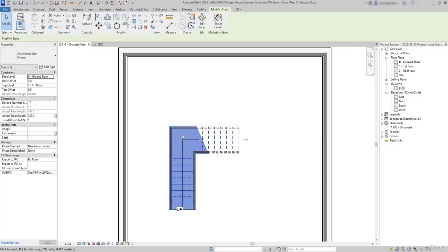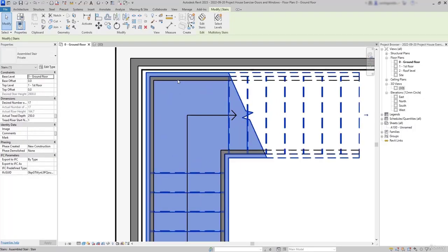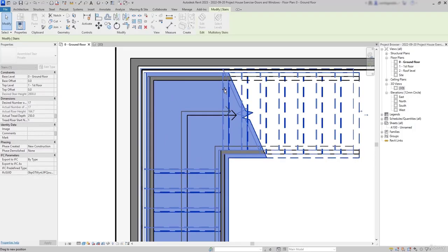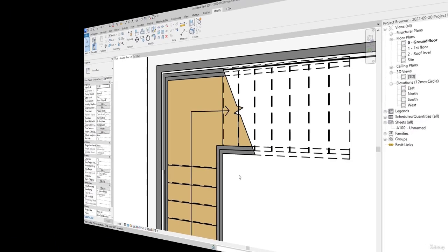Now I'm going to show you how to move the stair to one of the corners of this room. First, make sure the symbol Move appears. Then we can try to move the stair to that place, but you will notice it's hard to fit exactly on the corner. So in these kind of situations, the best is to use the Modify tools.